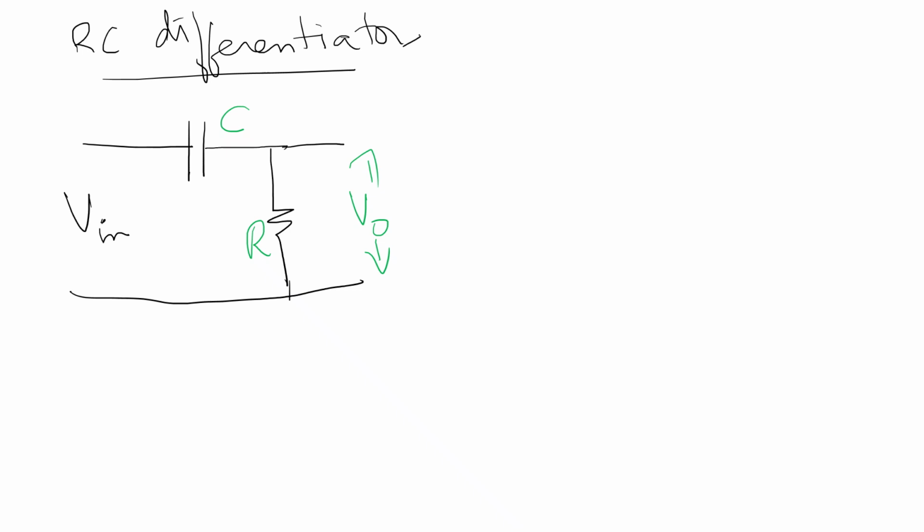If the square pulse is fed in here, the capacitor charges, and the output voltage observed across the resistor will be a spike voltage, wherein during the positive cycle it charges and then discharges in this way. Then, yes, we get a spike output. These spikes will help us in triggering circuits of thyristors. So T is the time period between the two spikes available.